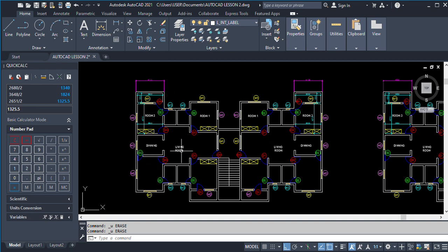You divide the building into panel by panel, in accordance with the code requirements. Some codes require that the length of your beam should not be more than this. If it is more than this, you have to check for deflection. You have to carry out certain calculations to be sure it is safe. Your span of slab should not be more than this. If it is more than that, you have to do some checks to be sure that it is safe.